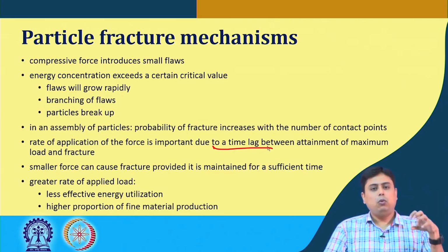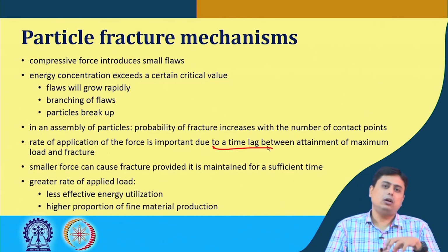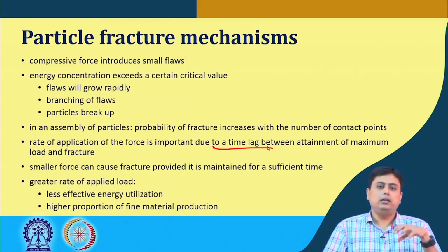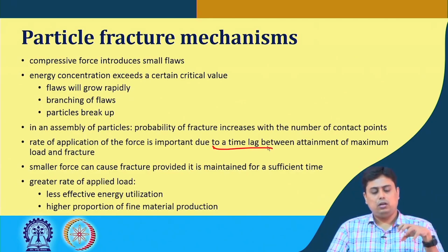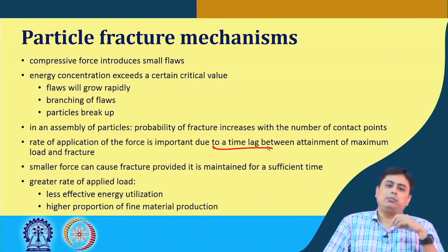It is the most inefficient process, because the energy you are supplying is not being converted into the creation of new surfaces. So, the greater the rate of applied load, the less effective the energy utilization, and a high proportion of fine material is produced.